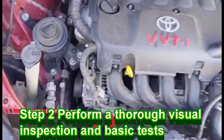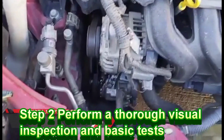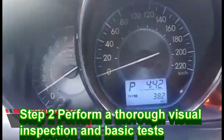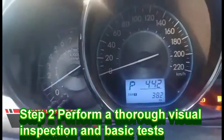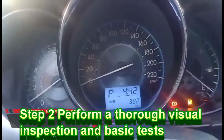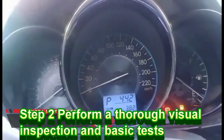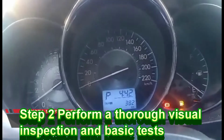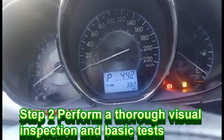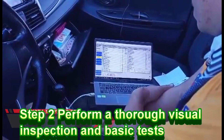Step 2. Perform a thorough visual inspection and basic tests. The visual inspection is the most important aspect of diagnosis. Most experts agree that between 10% and 30% of all engine performance problems can be found simply by performing a thorough visual inspection. The inspection should include the following. Check for obvious problems. Basics: fuel leaks, vacuum hoses that are disconnected or split, corroded connectors, unusual noises, smoke or smell.